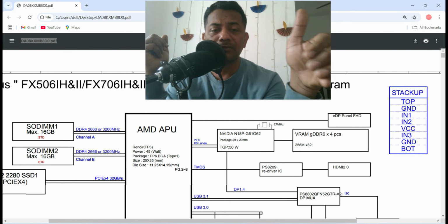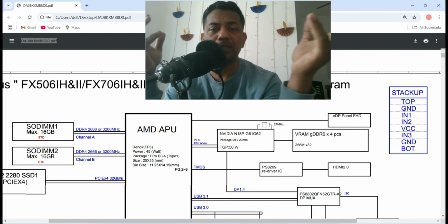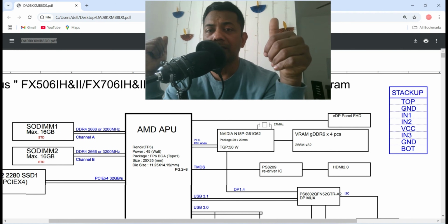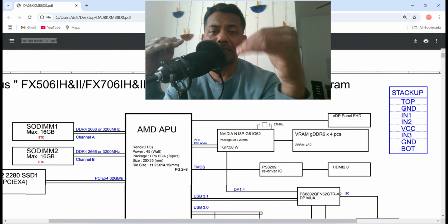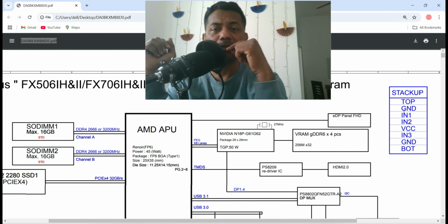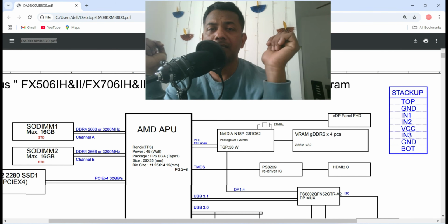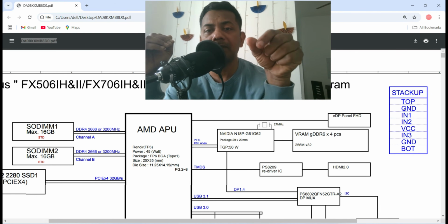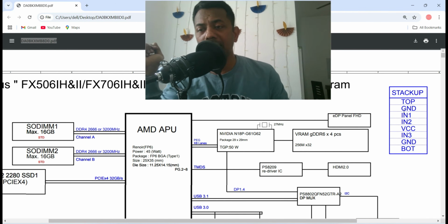It may be because of the APU's underside points, or it's burnt from a MOSFET or any other electronic component. Outside of the CPU we can easily identify it, but inside the CPU we can't. In case of overheating, the inside below the CPU might have burnt. That is also one chance. Or the ground connectivity may be joined. Because of overheating, the soldering lead might have burned and joined, and because of that also it was getting short. Okay, let it be whatever it may be.